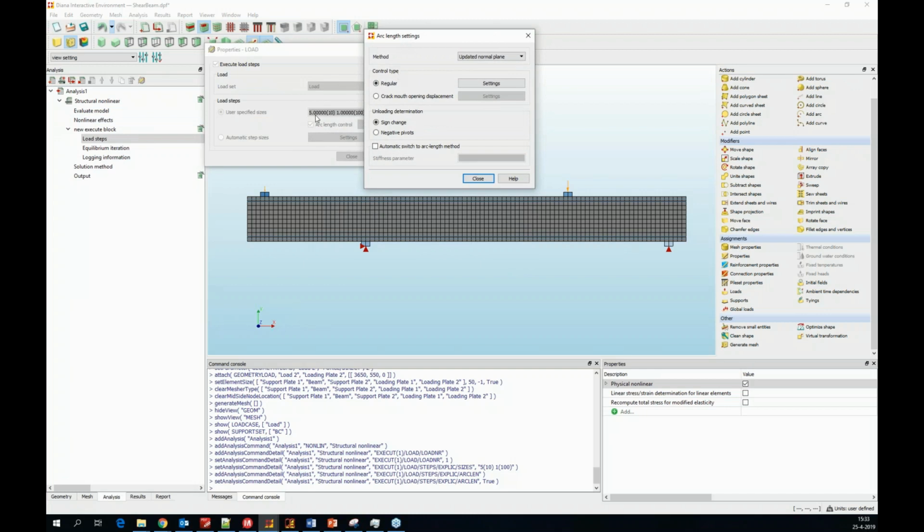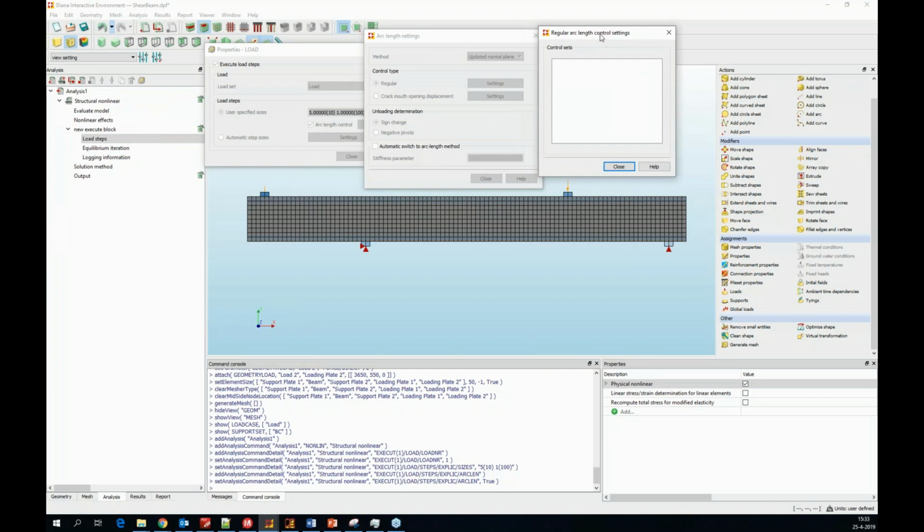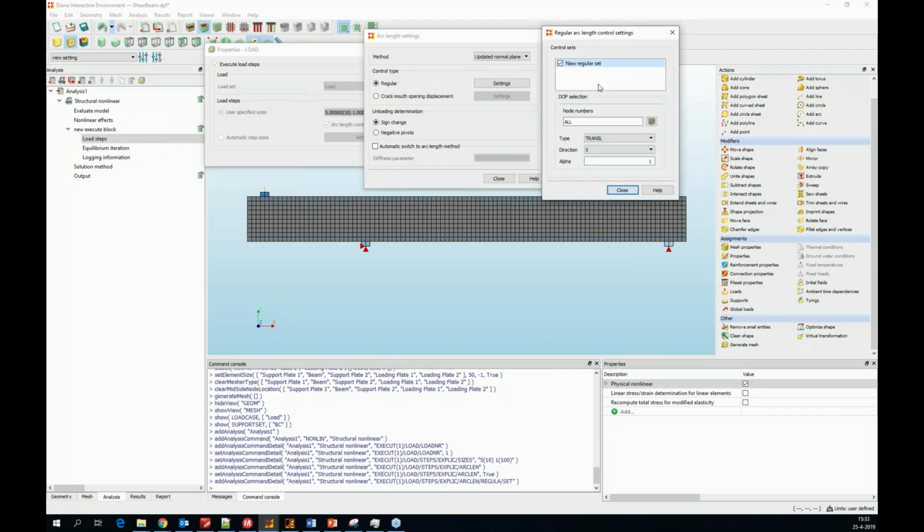And we cannot capture that if we do not use an arc length or displacement control. The other reason is that if you use arc length, when the nonlinear effects increase, you also see that your step size is automatically decreased. That's inherent to using the arc length method, but it's also a benefit.